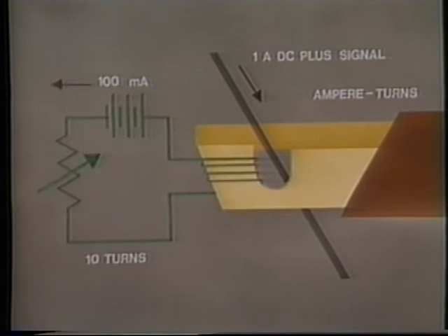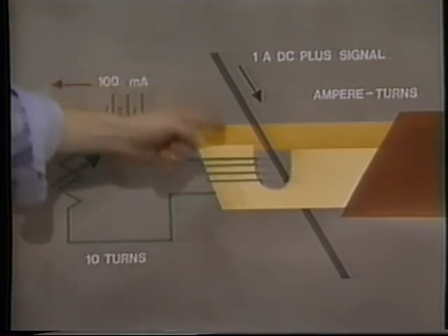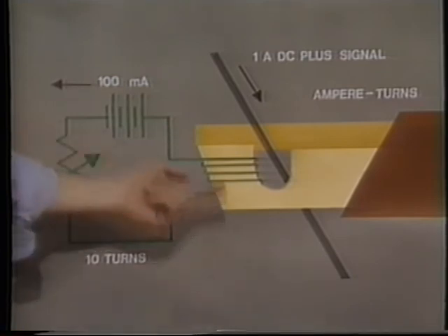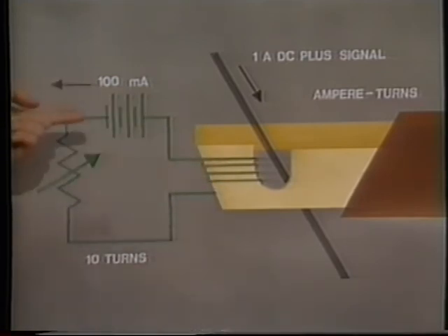Now that we've covered abstractly things you shouldn't do with a current probe, let's examine some of the things you can do anyway. Cheating is an engineering term for bending rules. In this case, we'll cheat to extend the input range of your probe. For example, if the DC signal component is saturating your probe and derating your AC current measurement, you can wind coil wire through the core and apply voltage to generate another field with opposite flux to cancel the effect of the DC and avoid saturating your probe.